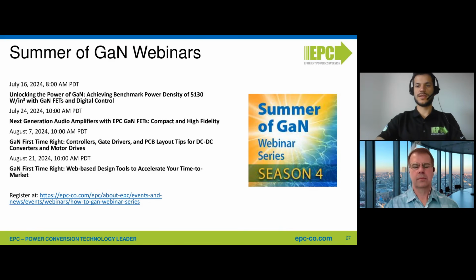These benefits are not only related to the device. The effect of the fact that you don't have recovery ringing might easily be hidden below a bad layout. I'm not sure if I answered, but it's something that is very tricky to answer and to debug in general. And then back to your presentation, yes, it's slew rate, but then how much ringing are you having, and how many harmonics? All those things are driving that as well.